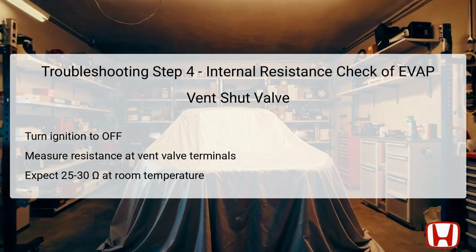Deviations outside this range, especially very high or infinite resistance, indicate internal damage or open coils requiring valve replacement. Accurate resistance measurements help confirm whether the component itself is at fault or if electronic control circuitry is to blame.